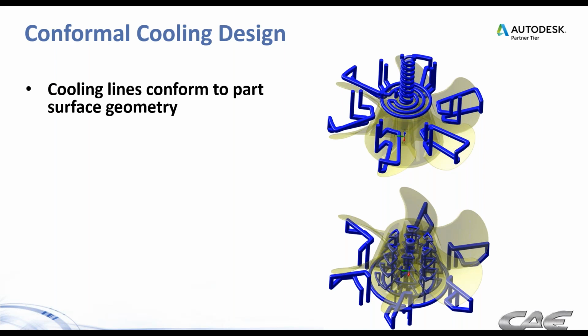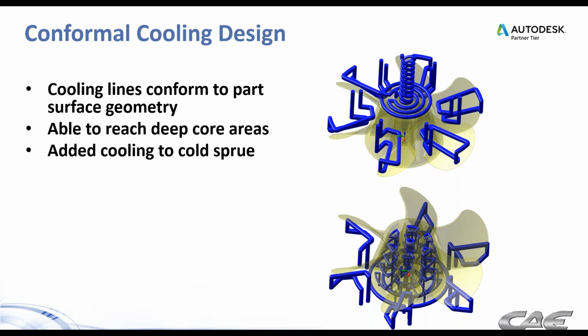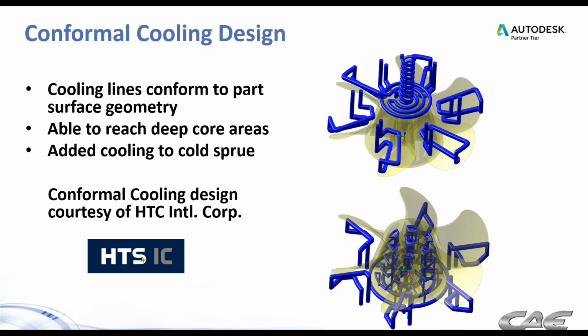The cooling lines conform to the part surface geometry. We're able to reach the deeper cores. We added cooling to the cold sprue as well. And as I mentioned, it's HTS Corporation that does this type of conformal cooling. So look them up if you're looking for another source for conformal cooling.